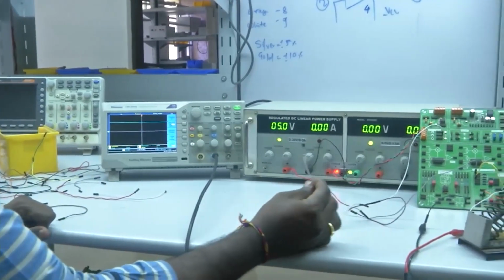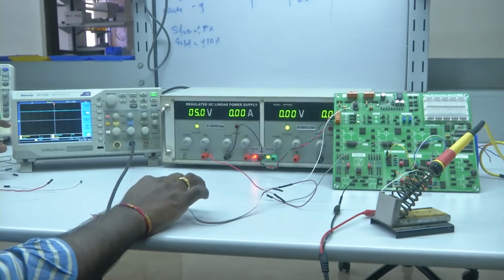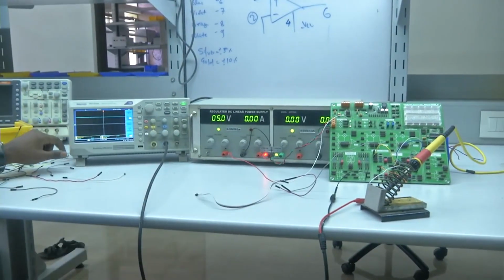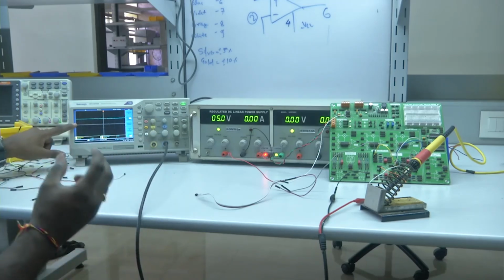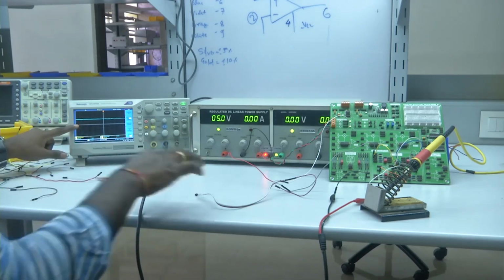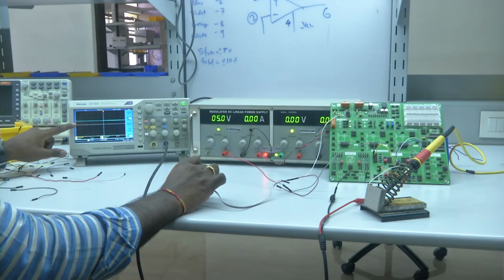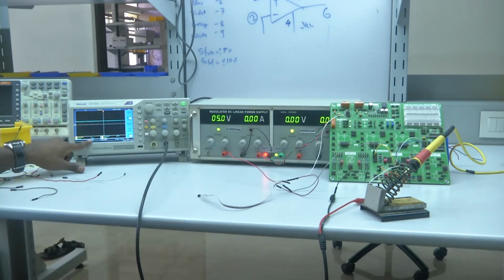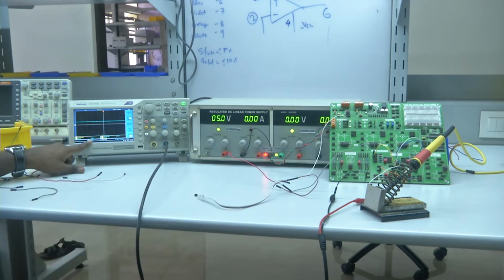Right? When I remove the temperature sensor, it starts cooling. Let it start cooling. So it started decreasing. So right now it is at room temperature. Since it was previously heated, it takes some time to cool down again. If I touch it, it cools very fast. So here we can see again it is coming down. So with this we can understand that we can use this particular temperature sensor, and by looking into the output voltage we can easily understand the temperature of the plant.